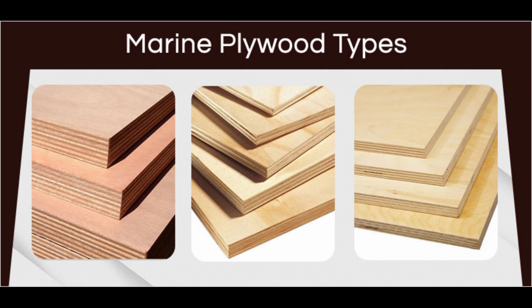Each wood veneer will be from tropical hardwoods and have negligible core gap, limiting the chance of trapping water in the plywood and hence providing a solid and stable glue bond. It uses an exterior weather and boil proof glue similar to most exterior plywoods.